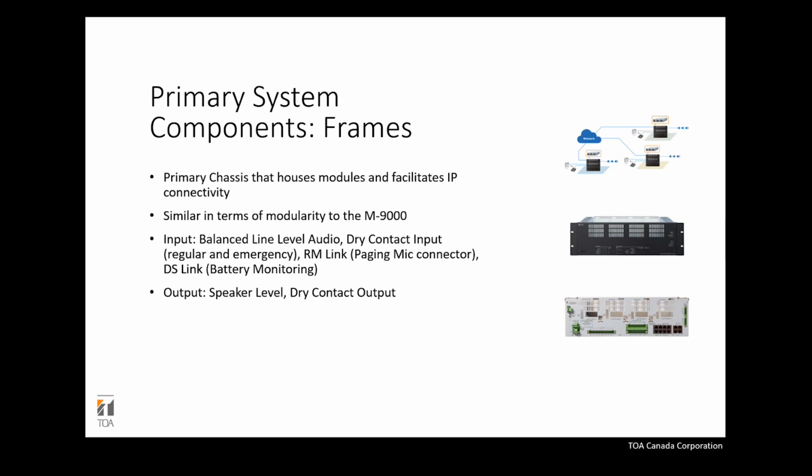Inputs include balanced line level audio. It also takes dry contact inputs, both for regular and emergency purposes. And the RM link, which is the paging mic connector that is proprietary to TOA, and the DS link. The DS link is the connection that you connect to the power distributor, which we'll discuss later, for monitoring of the power status and fault issues.